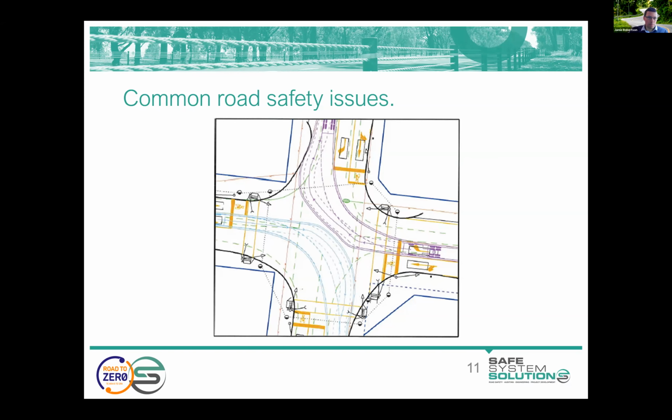So we typically prepare our swept paths in software like AutoTurn, and it really is open to a bit of manipulation. So it's important to know what you're looking at if you're reviewing one of these diagrams. The first thing that jumps out at me with this purple example is these little arrowheads along the center line of that movement. There's one there. They basically represent decision points. So a change in direction by the driver.